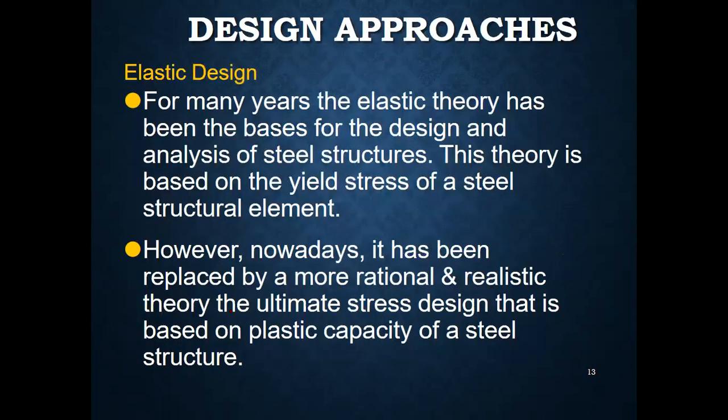Now, coming towards the designing aspect of beams, we have two theories or two design approaches. One is based on the elastic design, and the other is based on the plastic design. In previous years, the design and analysis of steel structures was mostly based on the elastic design or elastic theory, and this theory is based on the yield stress of steel.